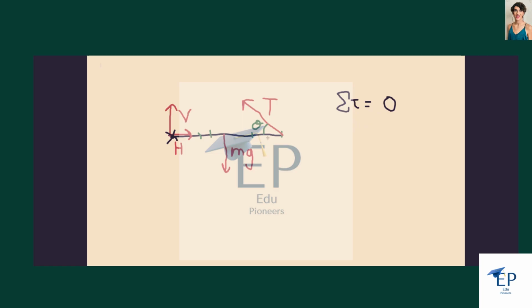So we've only got two torques here. We've got the torque from our tension force, which is going to be our radial vector of length x times the magnitude of the force T times the sine of the angle between them. Now, you'll notice that the radial vector really comes all the way along the bar and out past the end of it here.